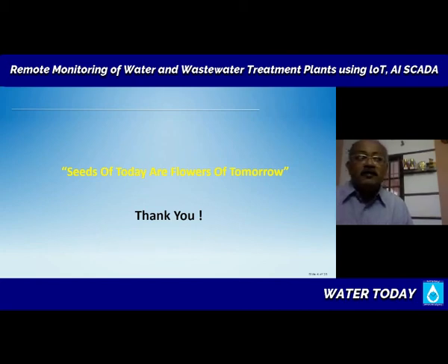Number 2 is what is available indigenously in terms of monitoring. Now, one thing that I can tell you is in terms of water quality monitoring. Even simple parameters like pH measurement devices are available in our country. They are fairly economical. But many of them say, no, I can't give you any guarantee for my sensor. So the electronics is okay, that we do very well. But the sensor technology with the glass electrode or the membrane and whatnot, those are not perfected, and manufacturers do not give you warranty for that.